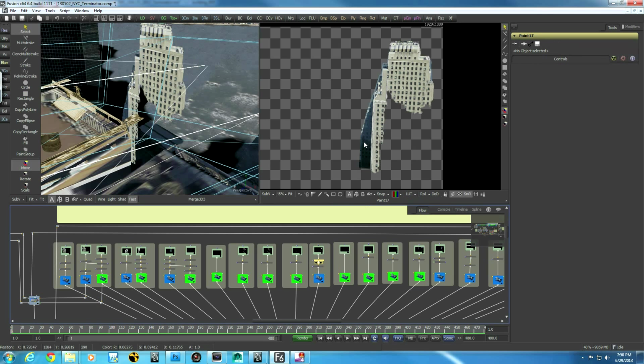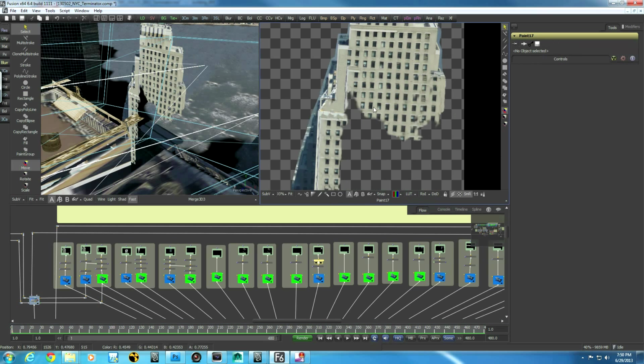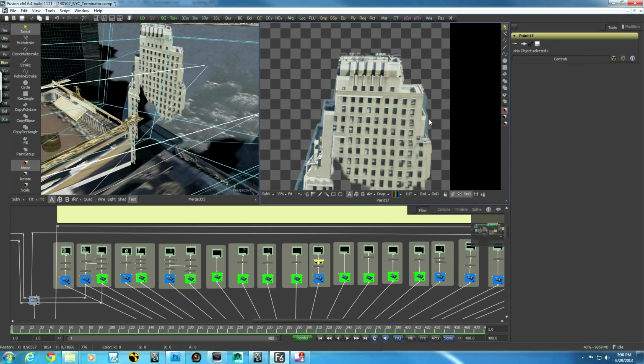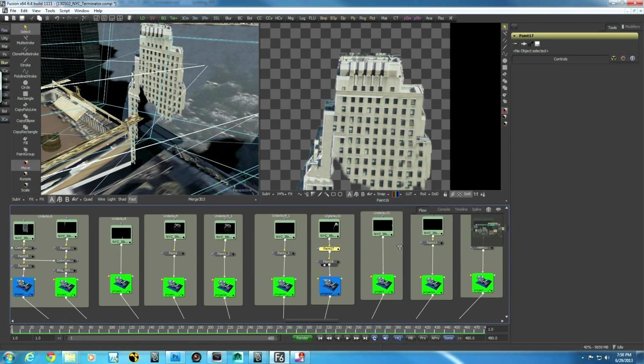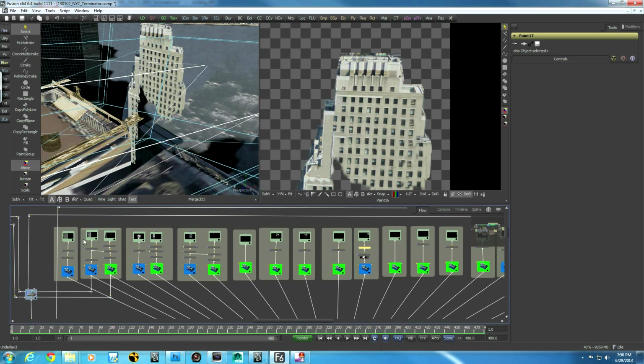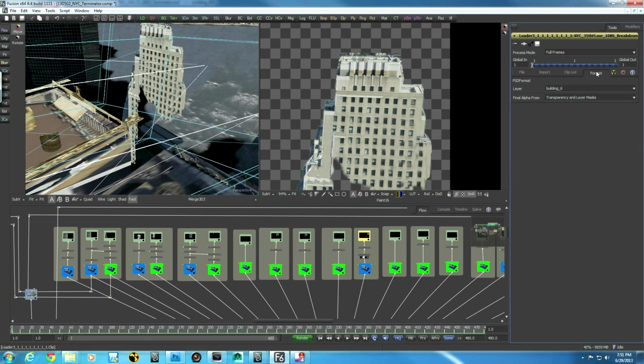And then I noticed that there is some leftover water that wasn't completely taken out in Photoshop, so I then applied the paint node to take that out. Now one thing to keep in mind is that all these images are basically the same PSD file. In the Format tab you can split the layers that you have in Photoshop, and whichever building that you need, you can use. If you have named them properly in Photoshop, then you can just use those layers here.